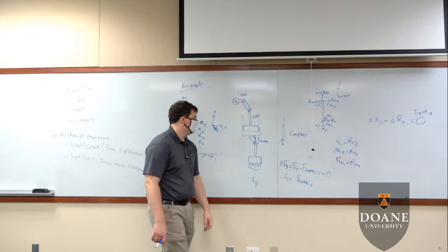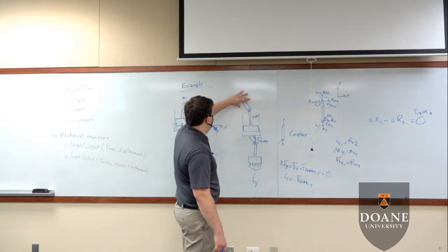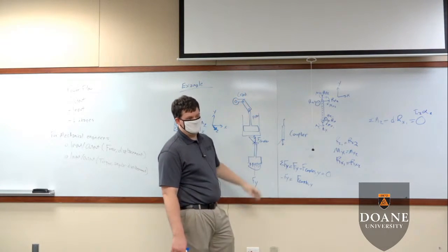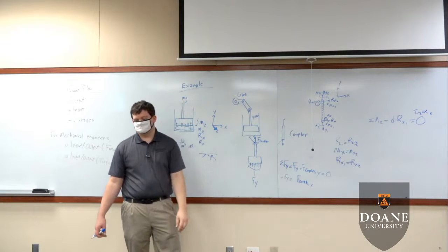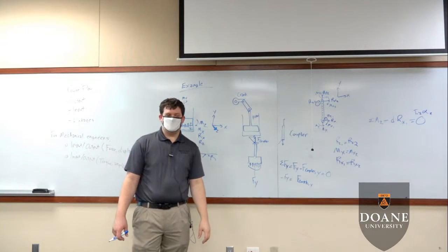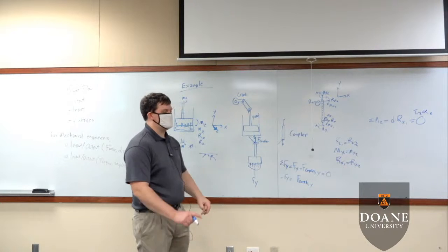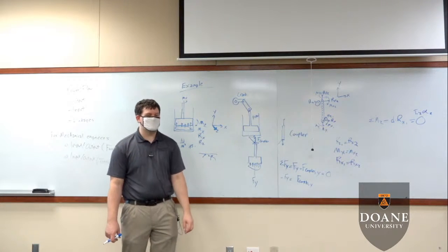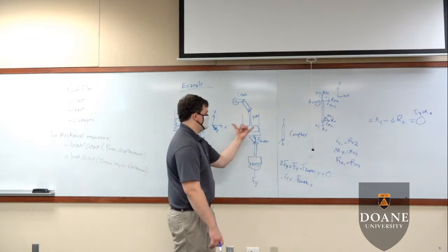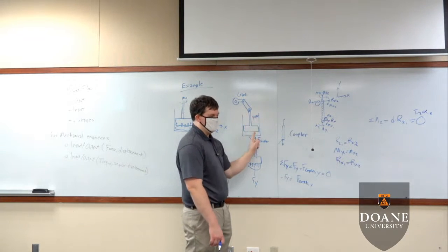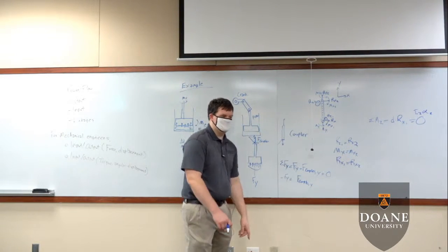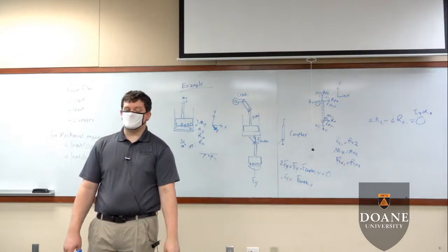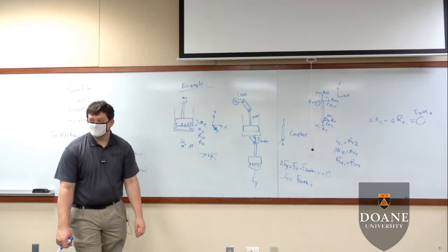Okay? If your coupler is horizontal to your piston, you have infinite force transfer that's theoretically happening in your coupler. You have an infinite amount of force because the vector has to be in this direction and all of your force is in the y direction. So yes, the math does break on this.